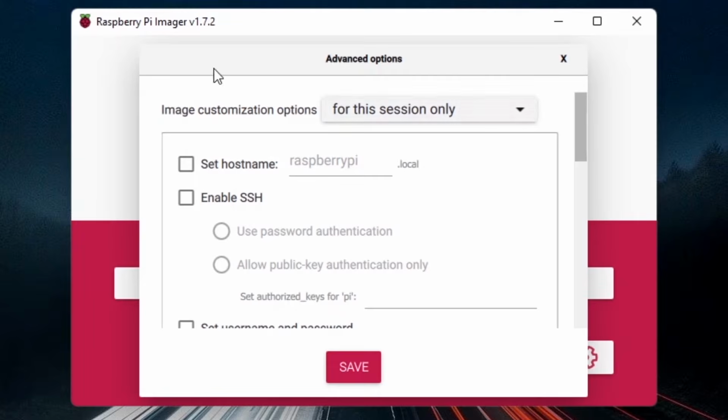Okay, so if you have an earlier version, please download the new one because you would not have this option, these settings. So what do we do on this menu? You're gonna click on enable SSH and leave it like this. Okay, we're gonna use SSH to get access to the Raspberry Pi using the terminal, and I'm gonna show you that just a bit later. And from this, we will be able to configure everything, for example, get access to a remote desktop, etc.